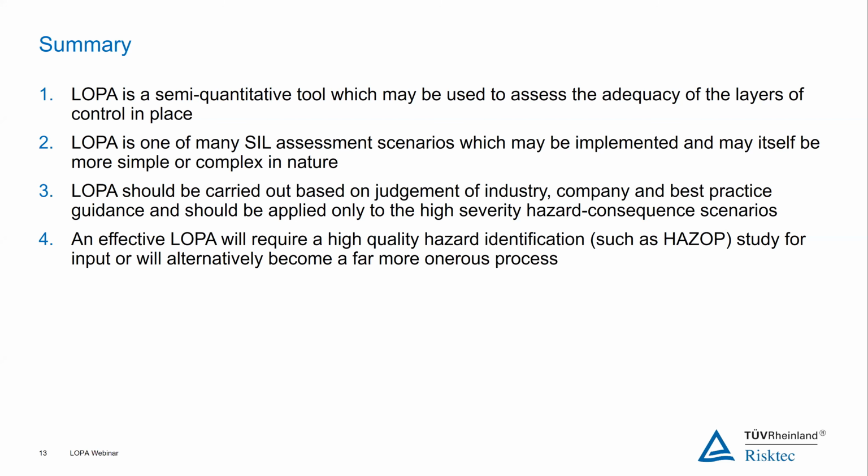Whether or not we should carry out LOPA should be based on judgment, the judgment of competent people such as yourselves, taking consideration of industry and company best guidance, industry best practice, and should only be applied inherently to our high severity hazard consequence scenarios, whatever definition we may have given that within the company or based on best practice.